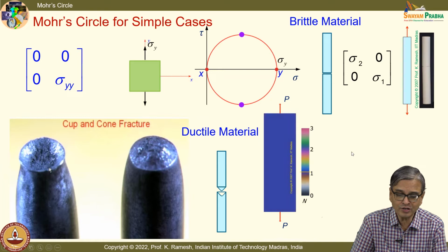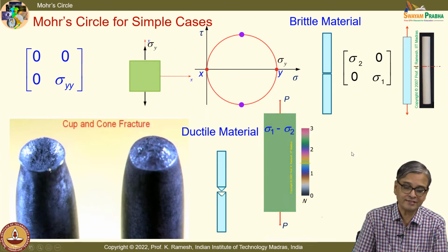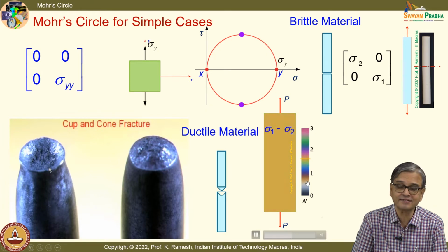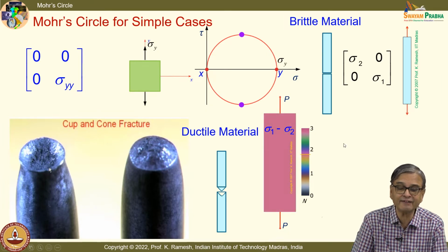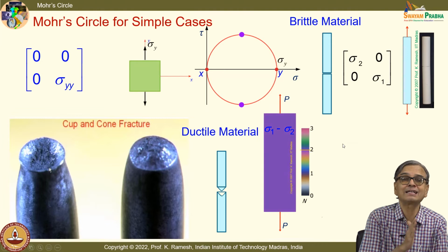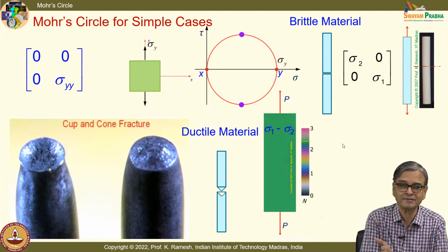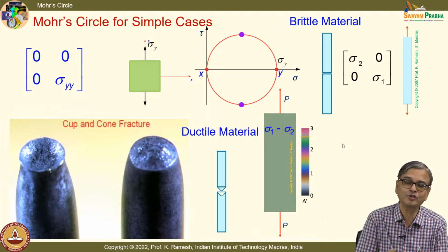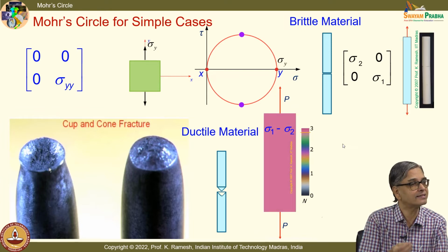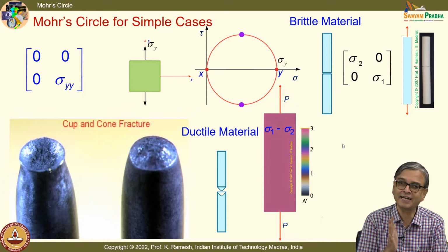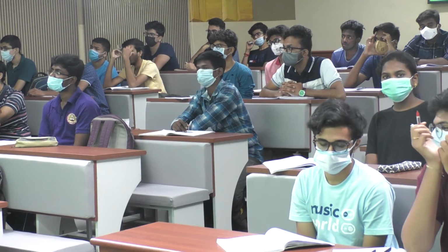But if we go to crystal optics and develop systematically the way photoelasticity provides this, this basically gives contours of sigma 1 minus sigma 2, and in this context, sigma 2 is 0. So, it is one and the same as sigma yy. Is the idea clear? Okay.